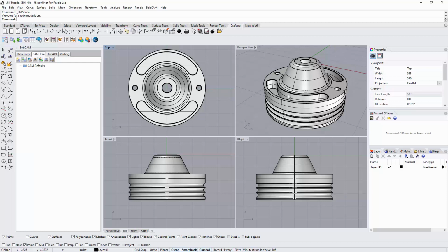We're also going to go in and cut these pockets on the slots here, as well as drill all the holes. Now we won't be able to do these side areas here because we don't have any tools that are going to do that. And really, I would turn that on a lathe, just like most of this could be turned on a lathe, and then we could finish it with the mill afterwards.